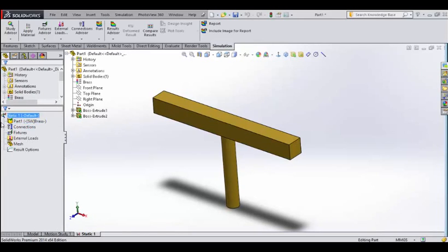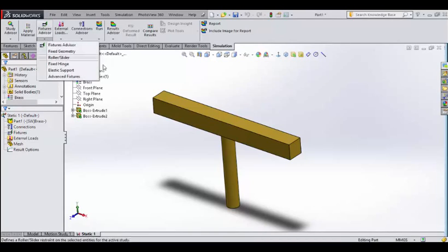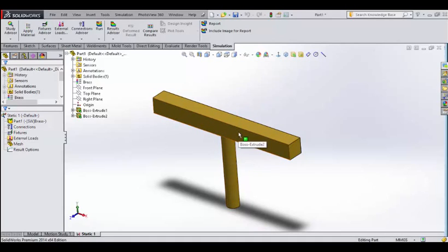Okay, here you can see new stuff, and all these grayed out buttons are visible now. So there are some steps you gotta follow, and SolidWorks has put them in really nice order. First of all, you have to apply material. In real life, what kind of material you're gonna use for your part? And secondly, you have to fix fixtures. For example, you have nuts and bolts or some other things you're gonna fix with your component, or maybe welds, or maybe a groove. So you can simulate that in a real-time situation.